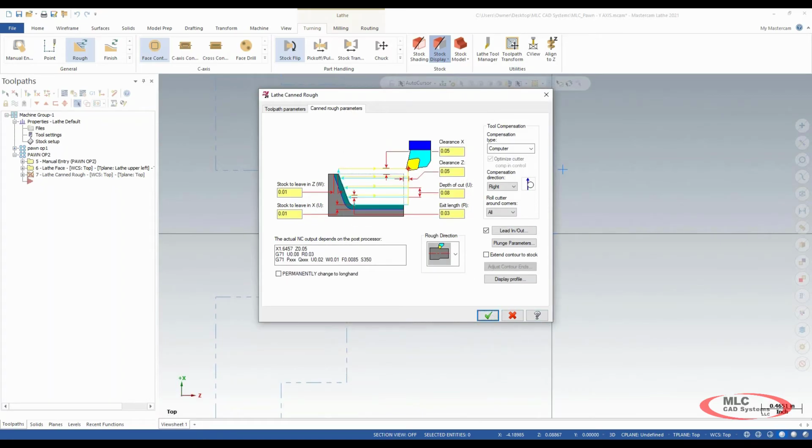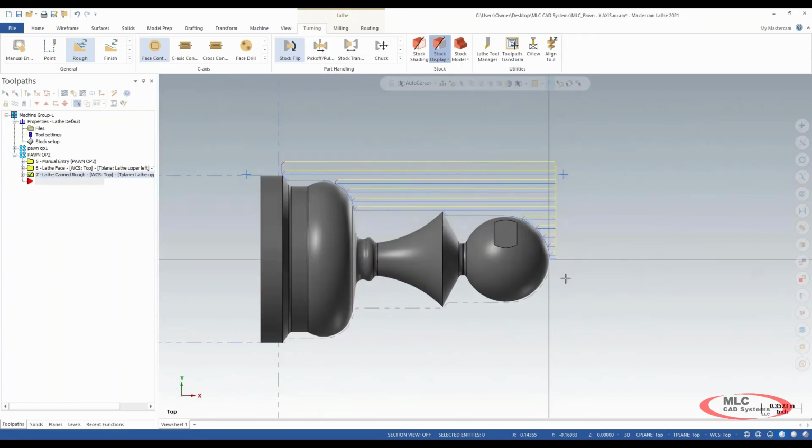And we're going to come back inside of these parameters. I want to talk a little bit about the options Mastercam has. Right now, Mastercam has given us a type 1 roughing operation for the OD. Mastercam also gives us the option to do type 2 roughing. Anytime we're doing a type 2 roughing operation, we're climbing back, but we're also climbing down and up into many valleys for our OD. Now I could simply use the type 1 roughing operation and actually come back and dig these out separately, but I've got a finish toolpath that we're going to discuss here that will cover that as well.